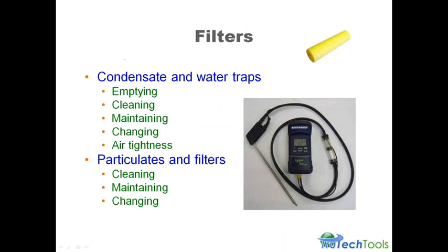I do change my filters out when I see they're getting totally saturated with water, just because it slows the reading down on the analyzer, and I like it to read as fast as possible. But you don't have to change the filters out. What I'll do is pull the filter out, put a dry one in, throw the other filter in my box, let it dry out, and then use it the next time through.